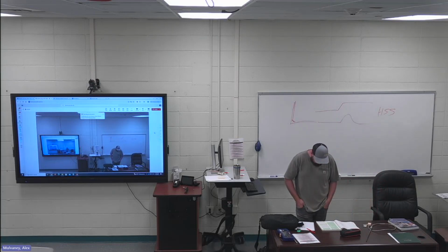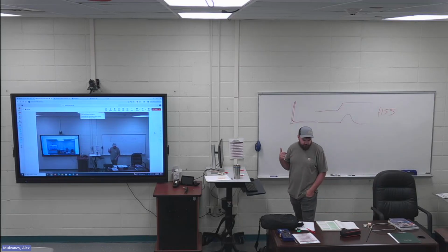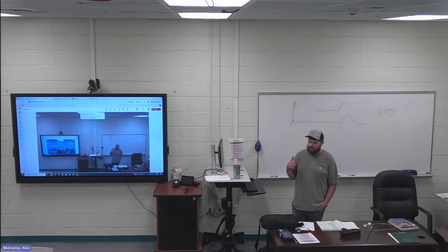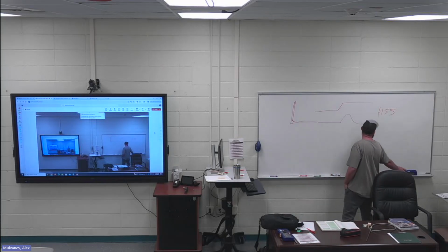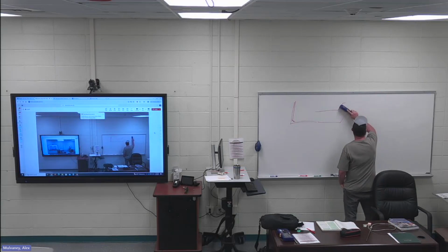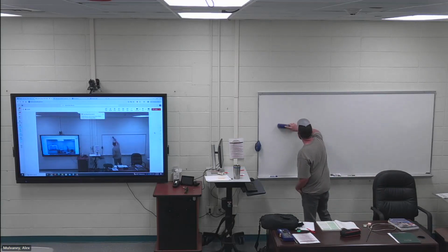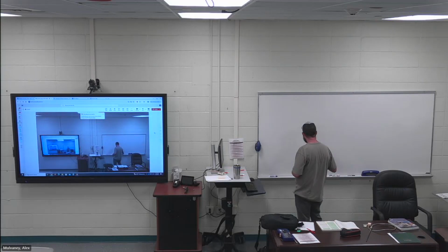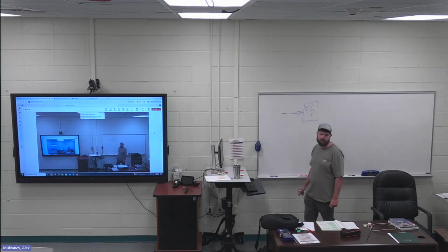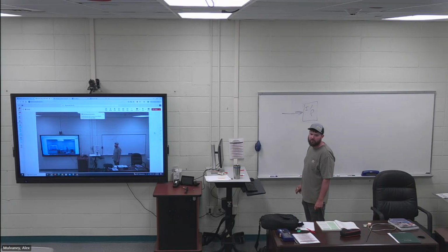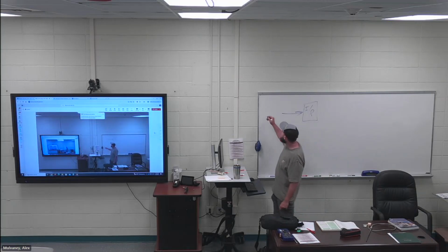Okay. Transducer. I don't have the highlight for transducer, but it converts one form of energy into another form of energy. What's the most common type of transducer in instrumentation? I to P. Good. I to P transducer, which means I have what going in? What does I stand for for electrical? Current.